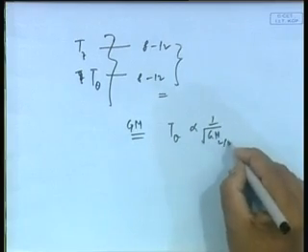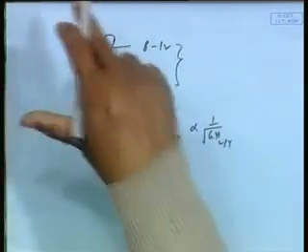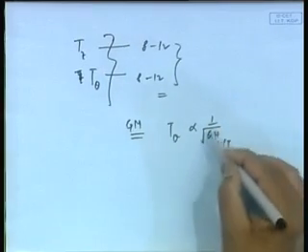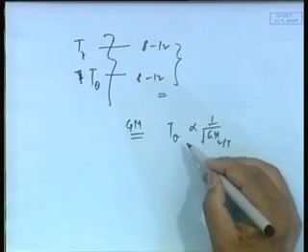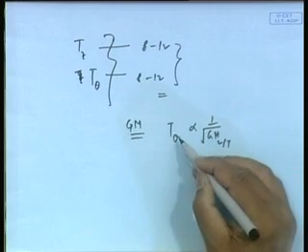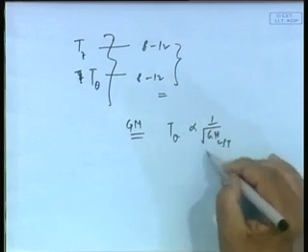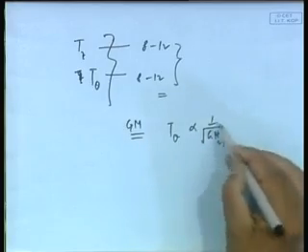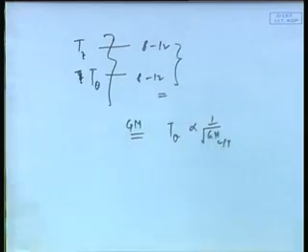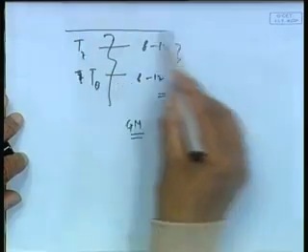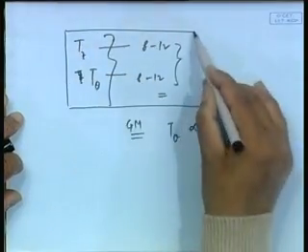Well, L or T in the case of offshore structure same, we will talk about that in roll. So what happens if it is too high, you have a very high GM means period is low, but I want to have this high, therefore I must reduce it. This we will see later on.